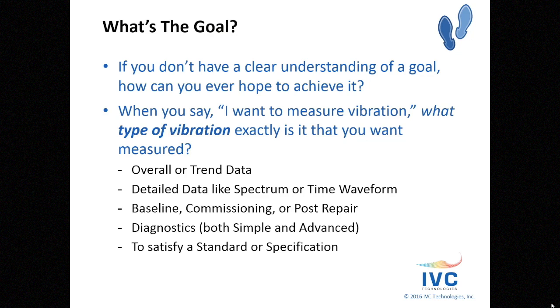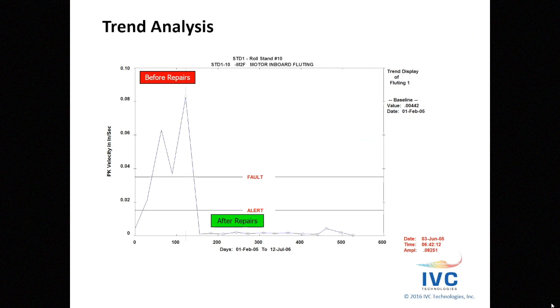Are you looking at measuring baseline or commissioning or post-repair data? Are you doing diagnostics, and that can fall into both the simple category or advanced? Or are you testing to satisfy a standard or a specification? Those can also have some specific requirements for that test that may be defined by the OEM. All of these things come into play when you're figuring out what you need to do before you actually get to the part of doing it. Here's a simple example of some basic trend analysis where we can see before repair levels, and then you can see the trend drop to after repair levels.